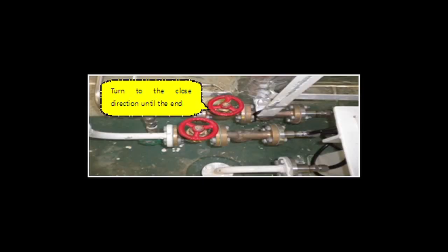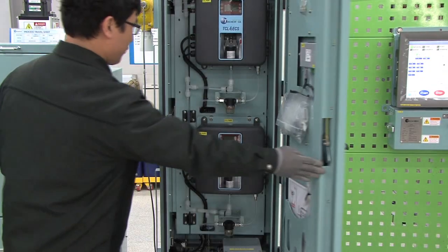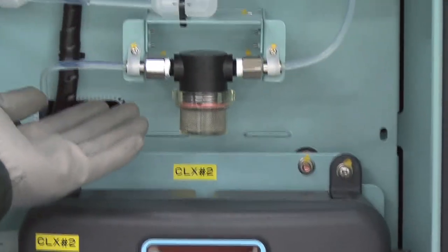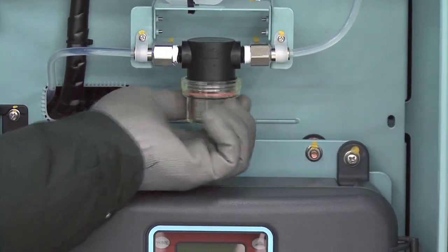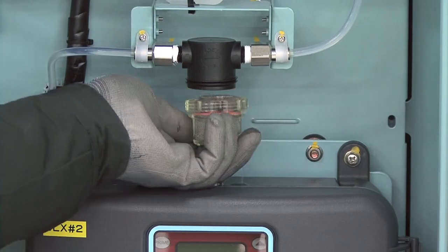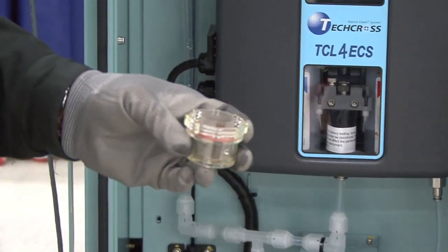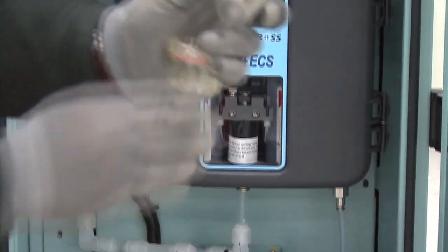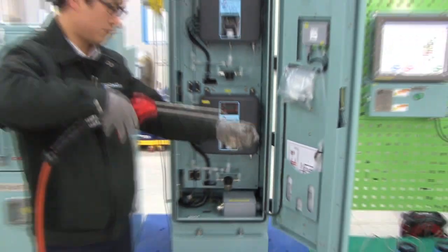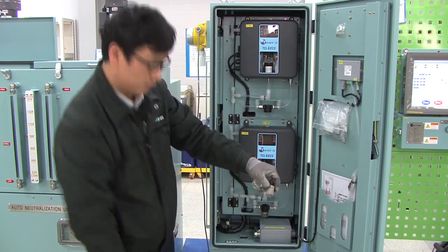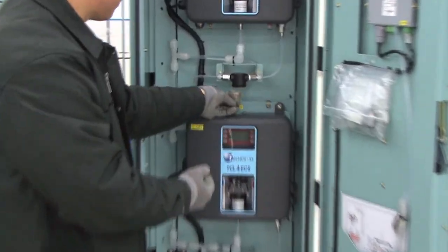4. Close TSU valve and remove reagent. Step 1. Close sampling valves port 1 to 3. Step 2. Disassemble CLX filter of TSU. Remove all the sampling water and clean up strainer. Reassemble CLX filter.